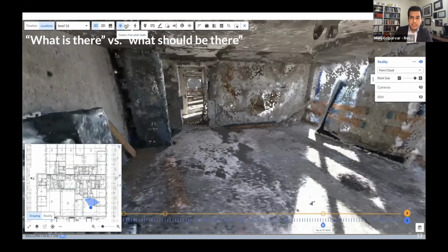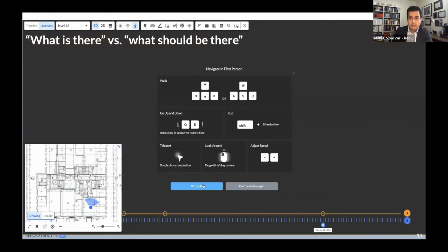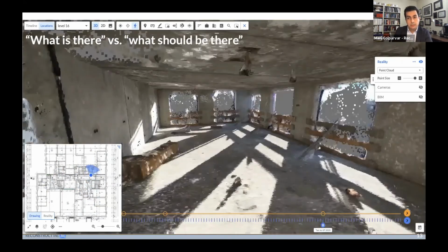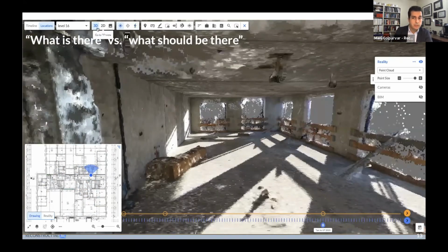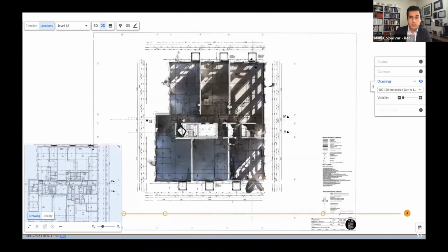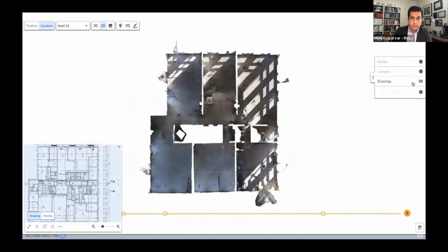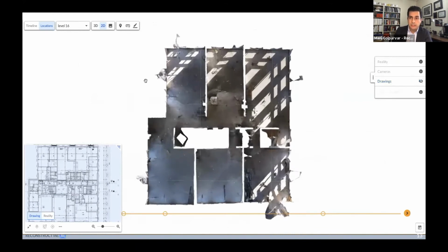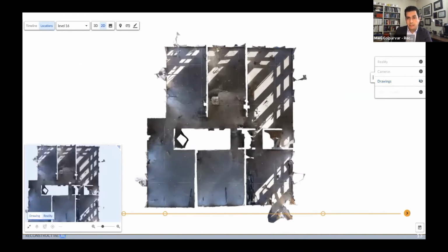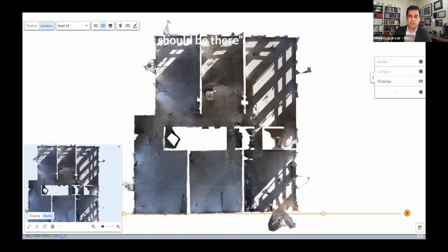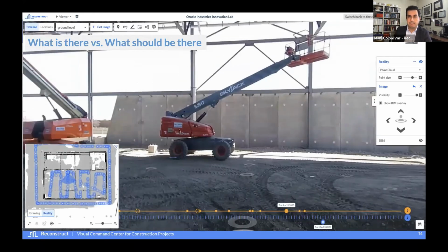So this is the kind of point cloud you can get from the system. Oftentimes people say, does it replace laser scanning? By no means it does, but it does provide you with the ability of complementing it for medium resolution scanning. That means for day-to-day documentation and measurement, this is perfect. Both in 2D and 3D, it gives you the ability to check conduits, embedments, pipes and whatnot, but this is really not for flatness or levelness measurement. Again, ReConstruct supports bringing laser scanning point cloud data.